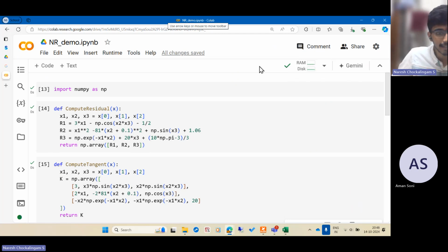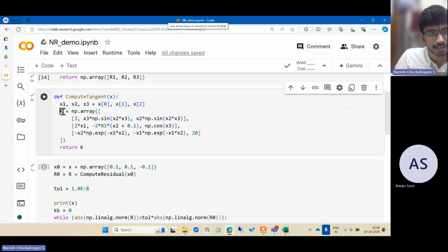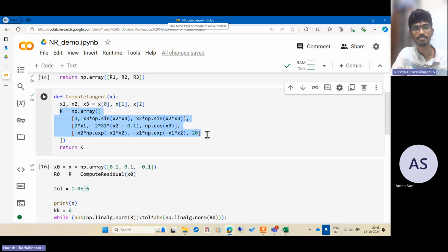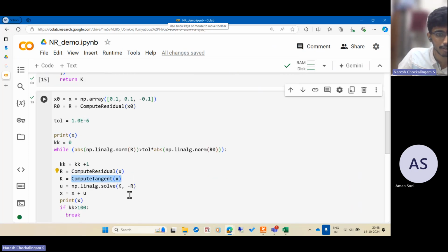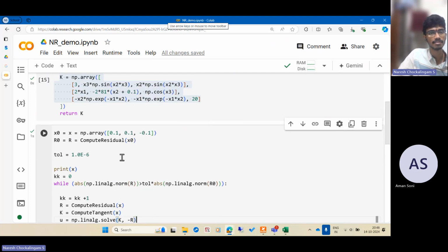So what I can understand is finding this tangent is very hard sometimes. For some really elastic, plastic is still fine. For some, when you have large plasticity and damage and stuff, finding the tangent is not easy. For finding the tangent itself, it may require a lot of iterations. In those cases, a Newton-Raphson requires a tangent. That's an issue, right? So Newton-Raphson without tangent is not going to work. So when we can't find a tangent, maybe it resorts to something like a bisection algorithm for solving the nonlinear equation.